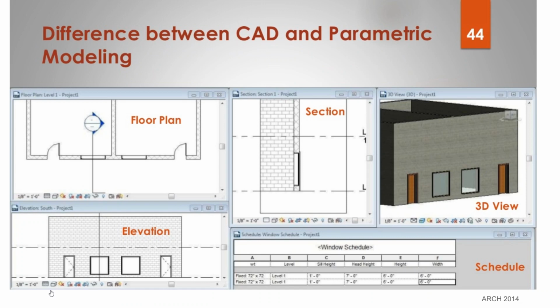And this is kind of an example of that. This is a little bit of an animated drawing. Over on the right-hand side, we have a building, similar kind of project that we're going to do, to start with a couple of doors and windows and some walls. And at the same time, the floor plan, the section plan, and the elevation are all automatically generated from this 3D model, along with a window schedule describing there's two windows, they're the same, and their dimensions.